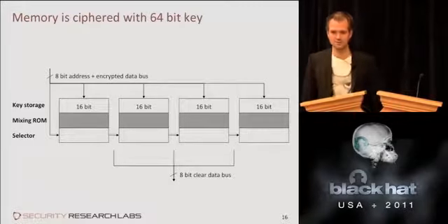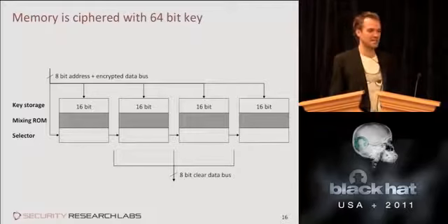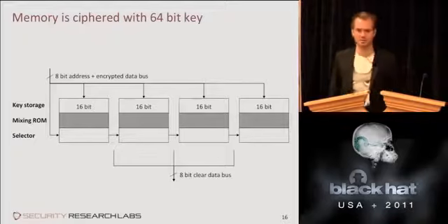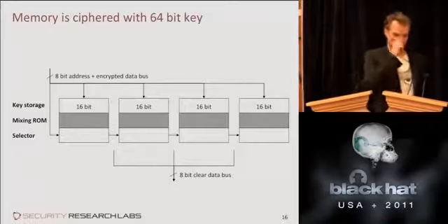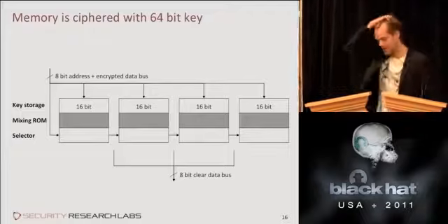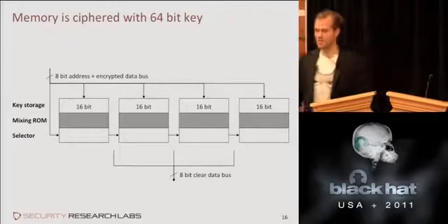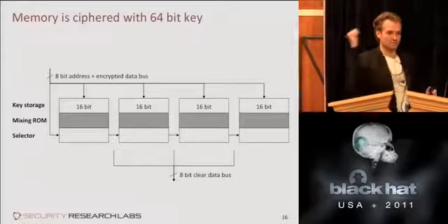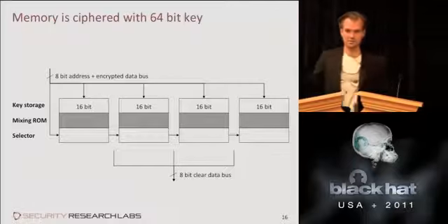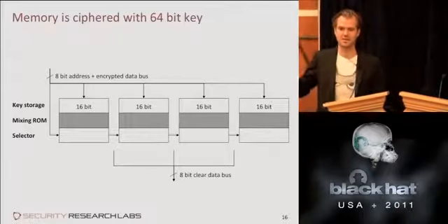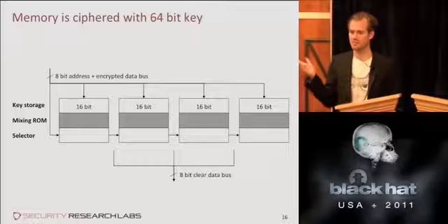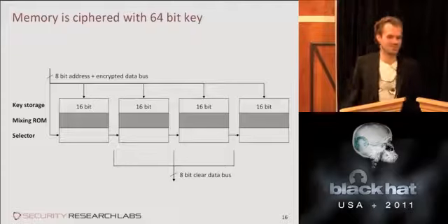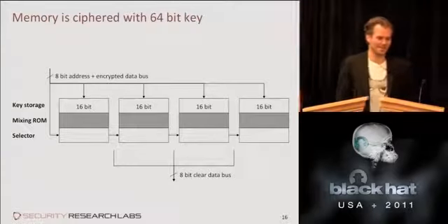Nobody has a design to do this well. Even the old DES, which is pretty hardware optimized, takes 16 clock cycles on this chip, so a lot longer than this. But long story short, there's this weak encryption function that decrypts the ROM. If you know this encryption function and the ROM contents, the only thing missing is the key, of course. Now, where's the key stored? In ROM, right next to the code. So if you read out the code, you get the key with it.